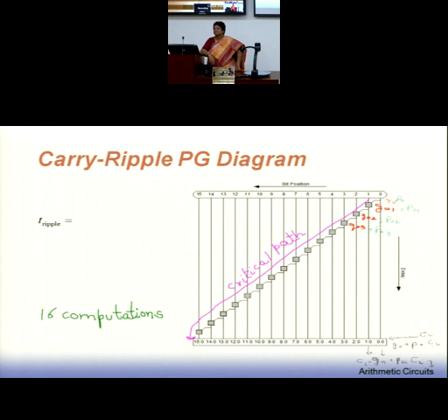So does this mean that we can actually come up with some optimum Radix value? Yes, you can do that. So is Radix 3 optimum or Radix 4 optimum? You can express everything in terms of n bits and then go for the minimization of that equation. You can find out an analytical result of which one is more optimum. So write the delay expression and then minimize the delay with respect to the Radix. Radix can be 2, can be 3, can be 4.